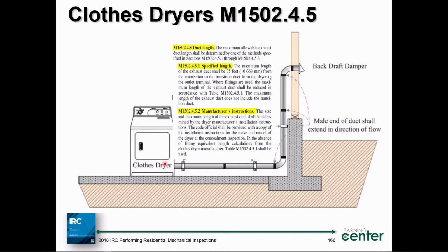Depending on what type of 90-degree fittings and 45-degree fittings you use, you will be hit with a big drop in pressure. If these are short radius 90s, you will calculate 5 feet of pipe for short radius mitered 90-degree fittings. There's a table in chapter 15 that'll show you those fittings.